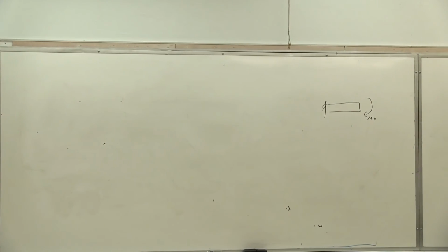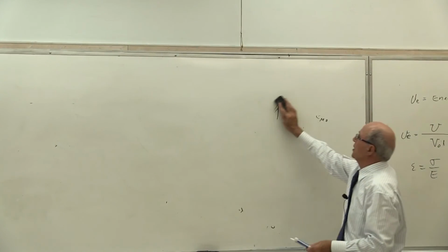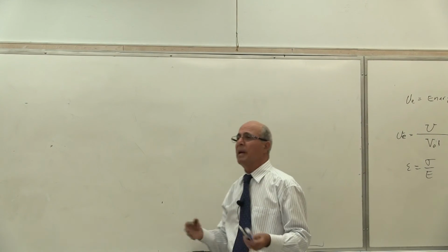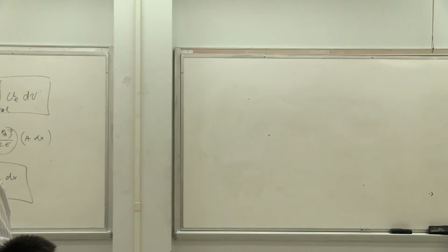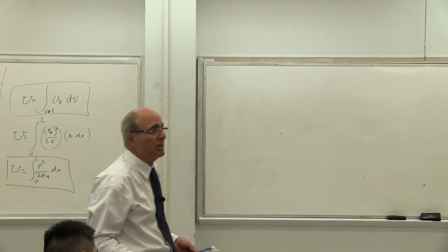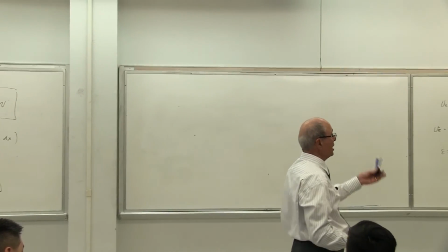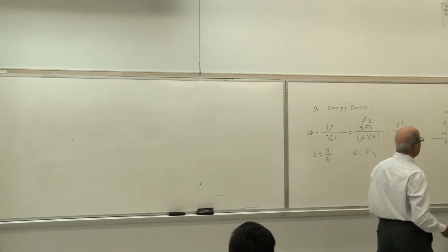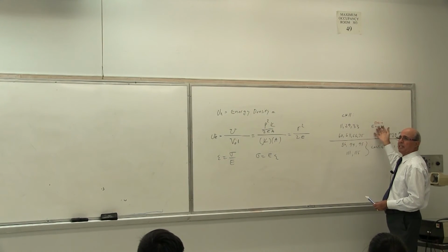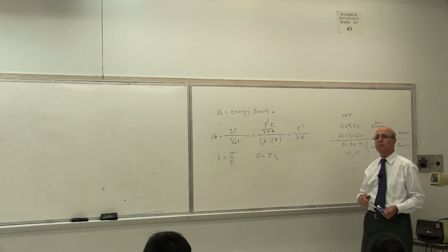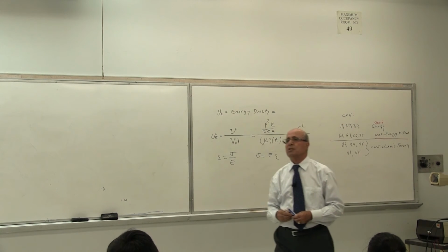It is like knowing the moment of inertia of the rectangle is 1/12 of base times height cubed, and you don't know the parallel axis theorem. Is this useful to you? No, it's very limited use. Without the parallel axis theorem, this is of very limited use. When I explain to you what the work of energy is, you will find out that there are lots of limitations here, and this Castigliano theorem makes it more general.